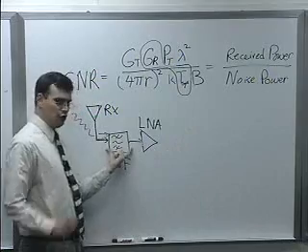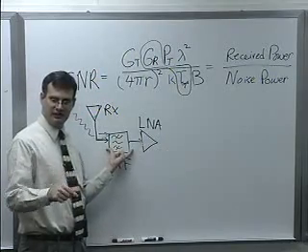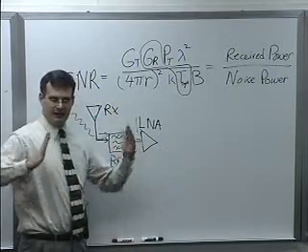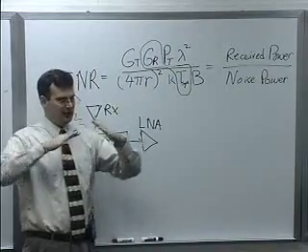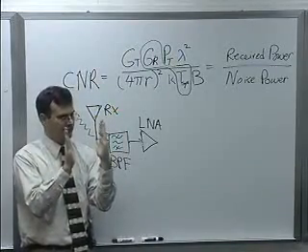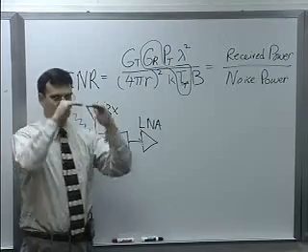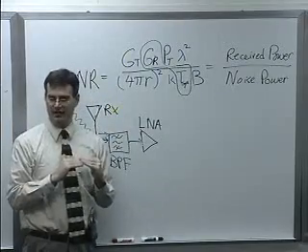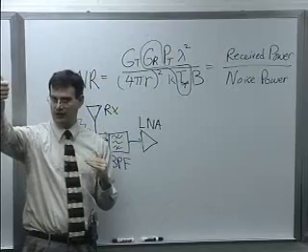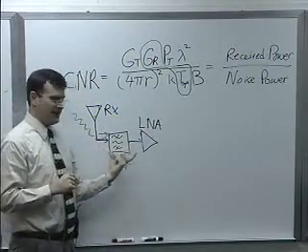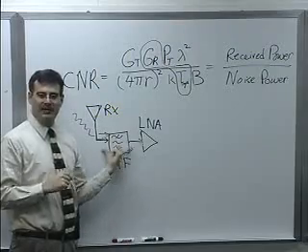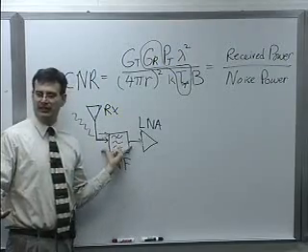This can't be too good of a filter because there's this theorem in filter design that basically says the tighter you want it, and the higher the Q and the tighter the filter characteristic, the lossier the filter gets. The insertion loss goes up. So you've got to be careful, because as we're going to see, this is the one place that you don't want to lose any signal.